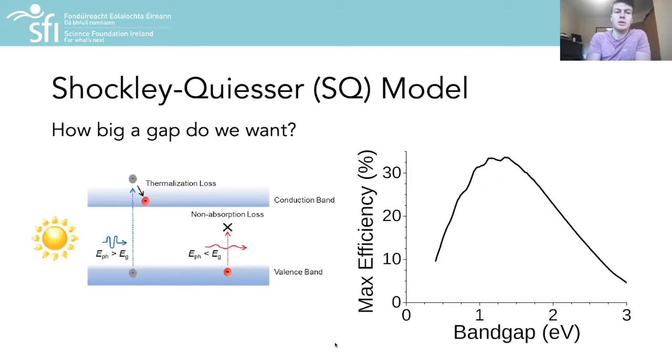So a key question is, what is the ideal energy gap for the maximum efficiency in our solar cell? So in 1961, Shockley and Queisser made a pretty good stab at this, deriving what we call the Shockley-Queisser limit for solar cell efficiency for a given band gap energy. So if you plot the fundamental limit to the maximum efficiency versus the band gap, they found that you get this sort of shape with a Goldilocks type zone between 1 and 1.6, 1.7 electron volts, where you can attain solar cell efficiencies greater than 30%.